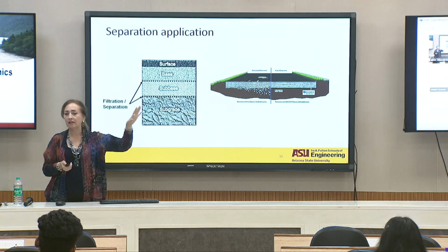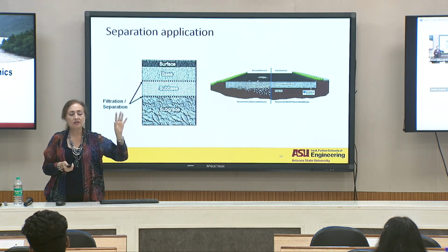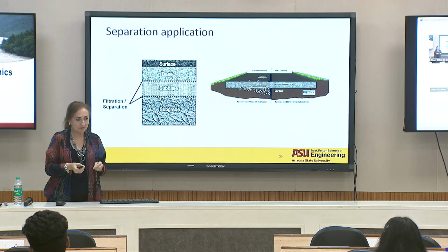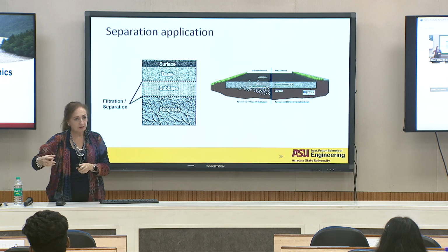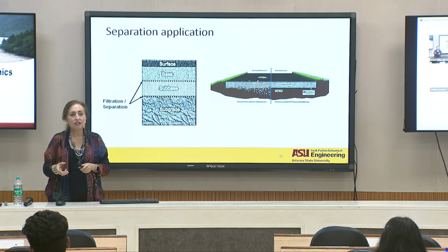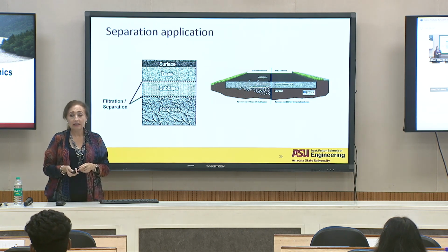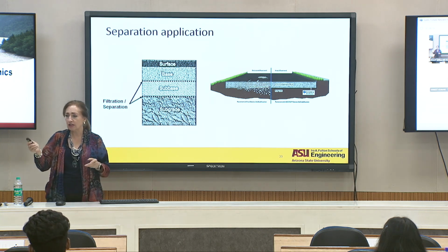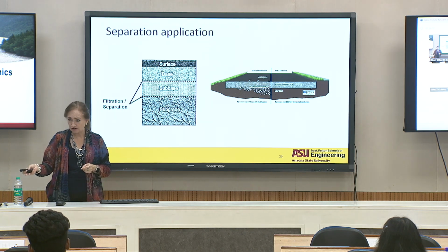Arizona has no rain. I'm talking about 6-7 inches a year, just multiplied by millimeters here. It's a very small amount of water. But you go there and core through a pavement, and you see water in that granular-based material. Not a 40-50% degree of saturation or less, but granular material that has 85-90% degree of saturation.